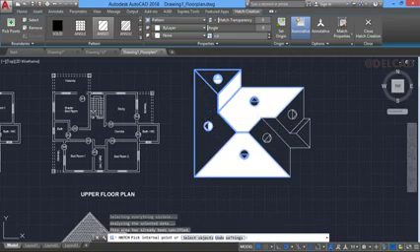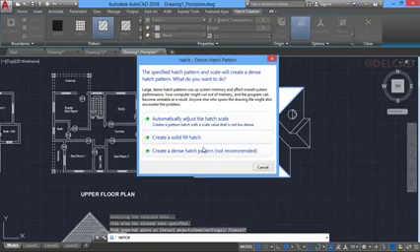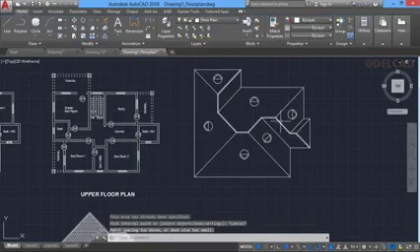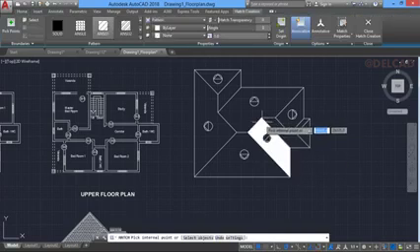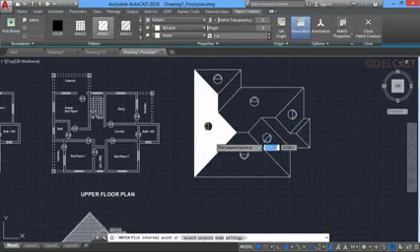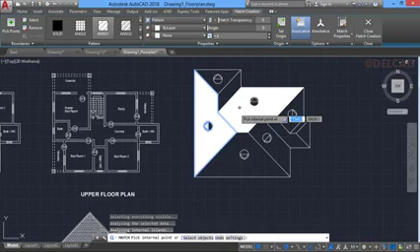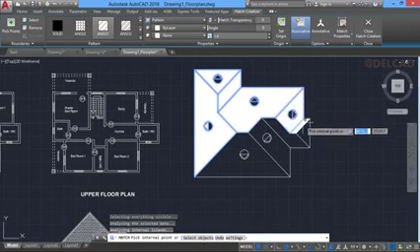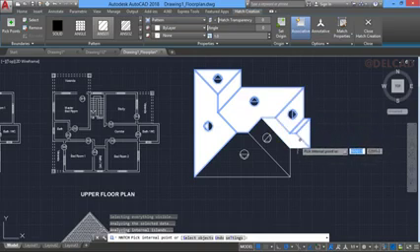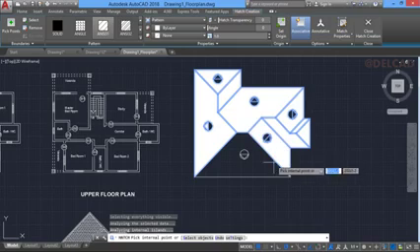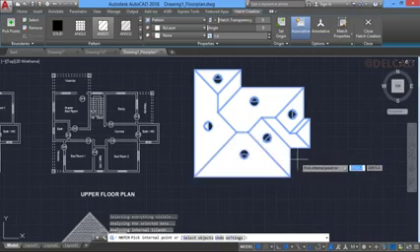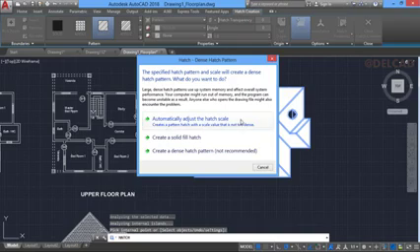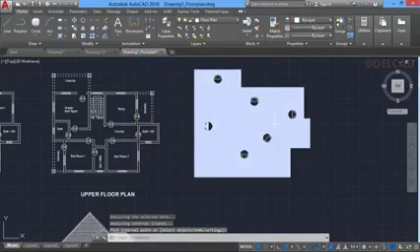Okay, let's escape, and then let's cancel this, and then repeat the hatch command again. So we'll apply hatch here and apply hatch here, and another one here, and one here, one here, again and again, and here and here and here. So now you can press enter and automatic hatch. So now you can see this is just looking too bold.